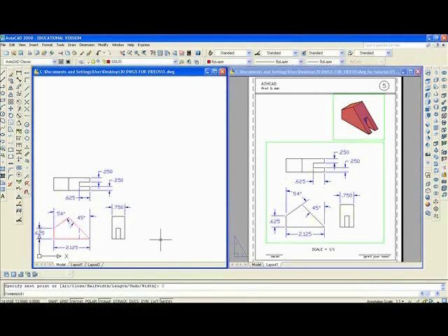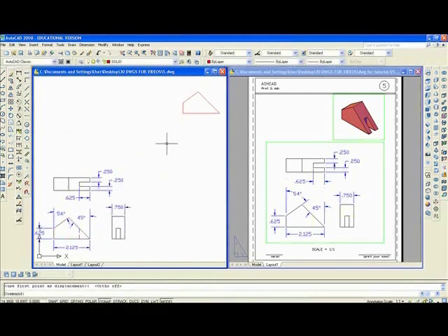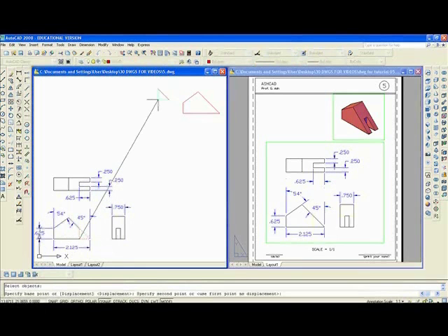C to close. M, enter, L, enter. And move that with ortho off up and to the right. You also want to trace over the little right triangle, so you take polygon, M, enter, L, enter, and move the right triangle up as well.